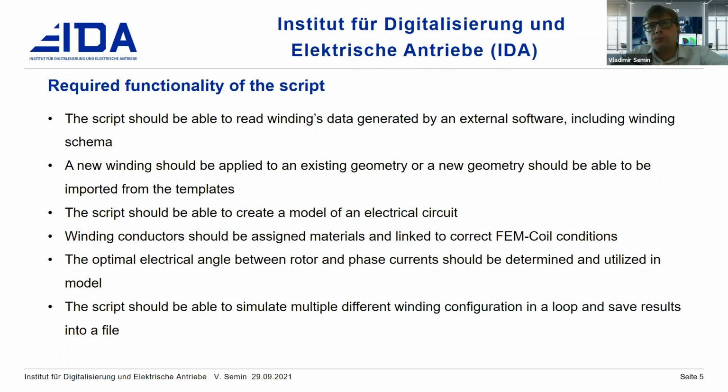The script should be able to simulate a lot of different winding configurations in a loop, one after another, and export the results with our goal values that we would like to investigate, like I said, the torque, for example, or the electrical losses.